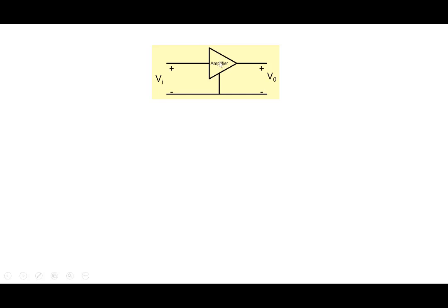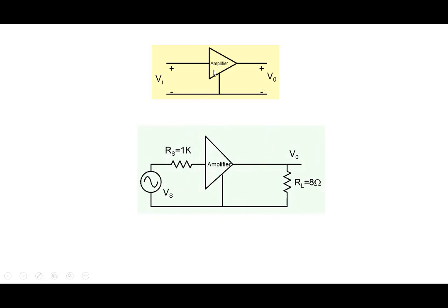Similarly, for example, if we have an amplifier here, so an amplifier again, look at it, has 3 terminals here, a pair of input terminals and a pair of output terminals. In this case, there's a common terminal here, so it's a 3-terminal device here. And again, if we want to use an amplifier in a circuit, we need a model of the amplifier. And note that the amplifier cannot just be represented in terms of a Thevenin's and Norton's, because we are talking about 2 pairs of terminals here, one pair here and one pair here.